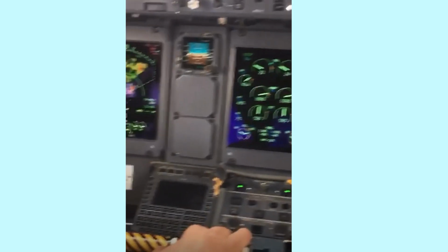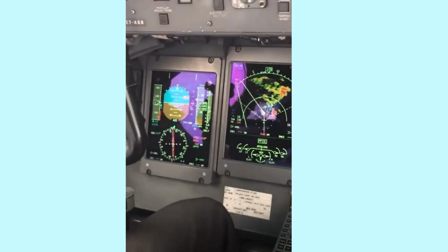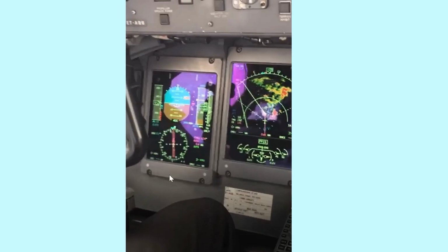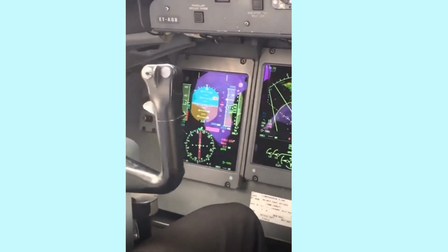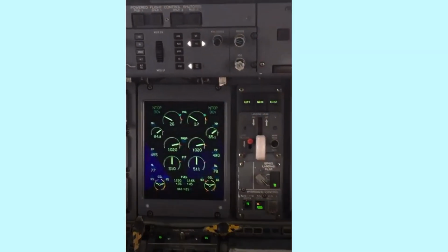You see I've increased the torque there, so the speed was coming here. You can see blurry images, but actually you can see clearly that the black wing bars are in between the horizon 0 degrees line and the negative 2.5 degree line, and the speed is almost equal to VREF to VREF plus 10 just by that setting. It's always a constant battle in the final phases. You can see here, there we go, 26-27% on both engines, which is matching the landing weight.